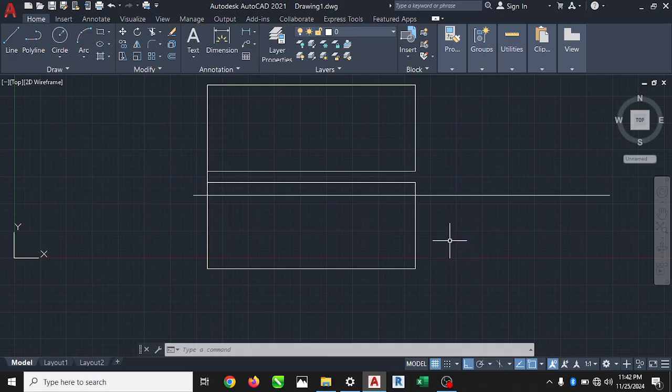So you can see actually, once I click on my polyline, it will highlight the whole line as a single entity. While for this one, each and every line, from each and every intersection, it cuts. For this reason, each and every straight line is independent unless you join it.